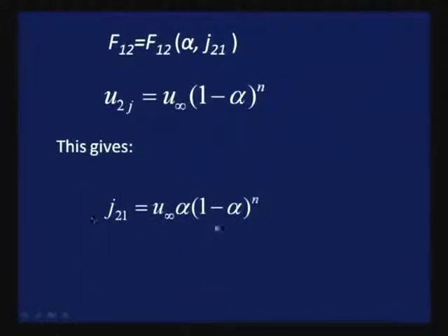So, this particular equation was obtained under the condition of steady state, inertia dominant, with absence of wall interaction effects and absence of particle-particle interaction. Now, when the particles come very close to one another, particle-particle interaction becomes much more important. And when it becomes important, the basic assumption on the basis of which I had derived the equation for the curve itself fails.